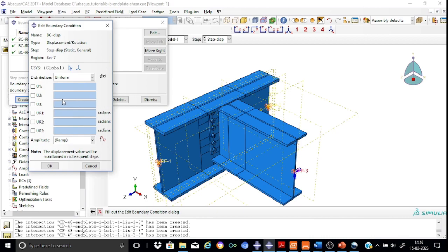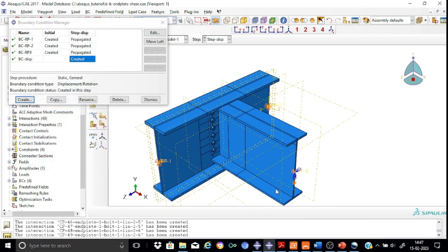As you know, we apply it in the y direction, so that is my U2. This is -5, downward direction 5 mm, and here I have defined the linear amplitude function as amplitude triangle. That's okay for me. So you can see that we have applied all the prescribed boundary conditions as well as the displacement loading at the points in this module.